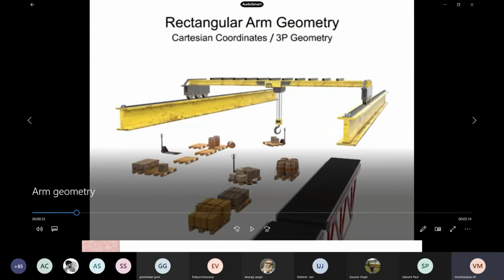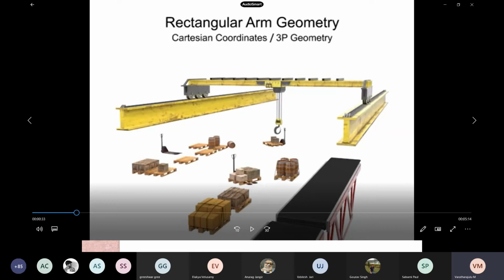That prismatic, please, does someone remember what is prismatic? We have already talked about the pairs, and we have introduced 5 different types of pairs. It is audible? Yes, audible. One is revolute pair, prismatic pair, cylindrical pair, spherical pair, and hook joint. Concerning the revolute pair, that has to be written as R. It has 1 degree of freedom.